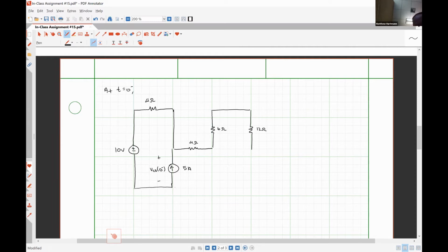Now, let me draw something here. All right, so the inductance is for sure going to be placed between that node that I've outlined in orange or red and this node that I've outlined in purple. Other than that, it really doesn't particularly matter how we express it. As long as it's connected between those two nodes, we're good to go. And we know that it needs to be connected between those two nodes because those are the two nodes that are shared by the individual inductors, right?